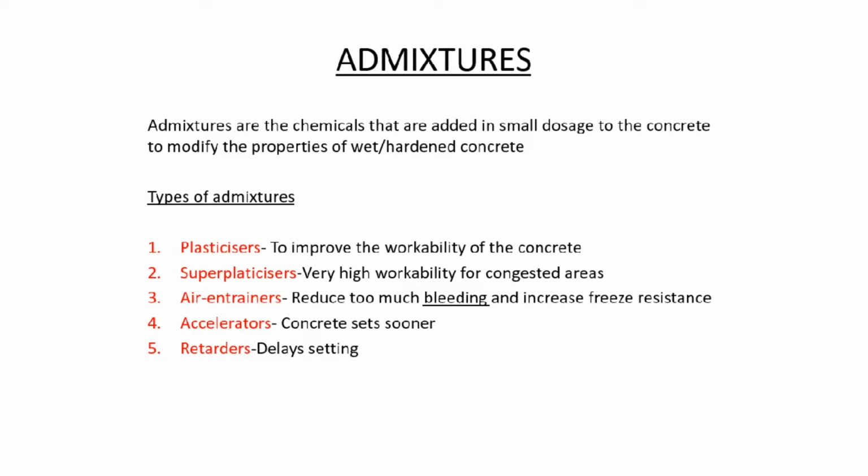Super plasticizer, as the word says, super, which means too much. Very high workability, especially in very congested areas. We use plasticizers to get a self-leveling situation. Air entrainer reduces too much bleeding and increases freeze resistance in concrete.